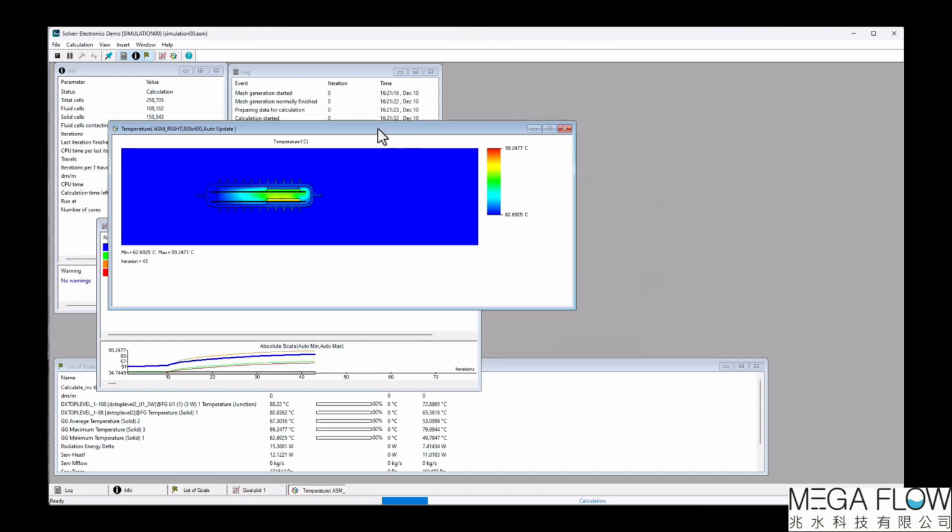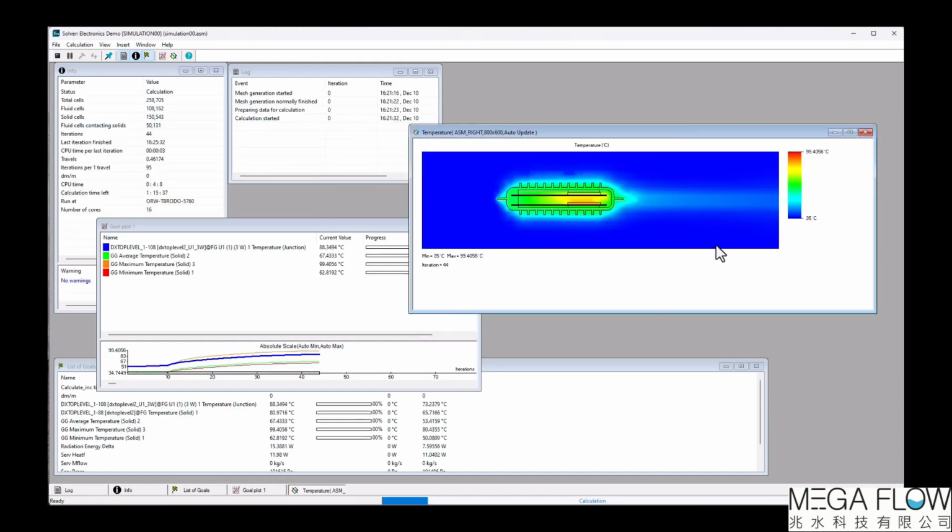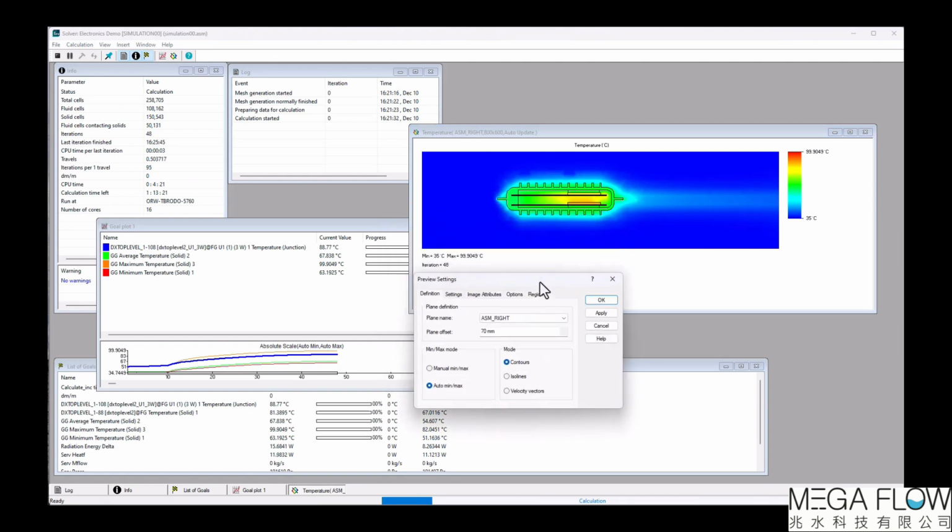Under settings, I'll change pressure to temperature. I'll up the resolution a little bit and hit OK. Now it's showing our whole computational domain size. I can modify that cut plot here. You can right click and go to properties. For one, I want to trim our cut plot, so I will reduce the Ymax size to 150.